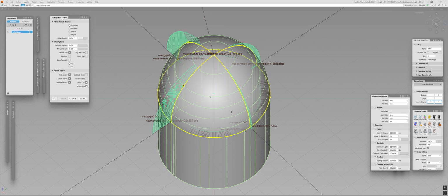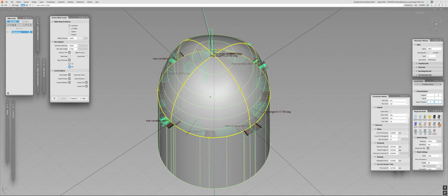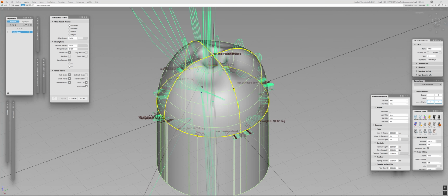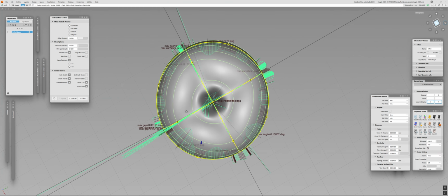So how do we fix it now? What can we do to fix this? First of all, of course, let's check keep continuity, and let's check maybe G2. Oh, what's going on? Well, you see, when keep continuity works on the surfaces, it's much more complex than its counterpart on the curves, because surfaces have two-dimensional domains, and curves have only a one-dimensional domain. So it can't really solve the continuity properly, especially when you have a degenerate point.